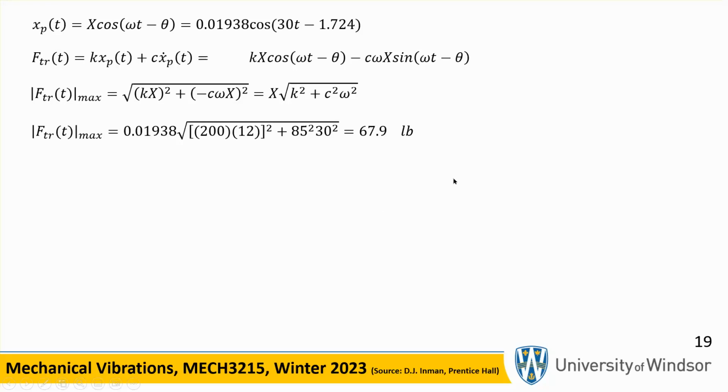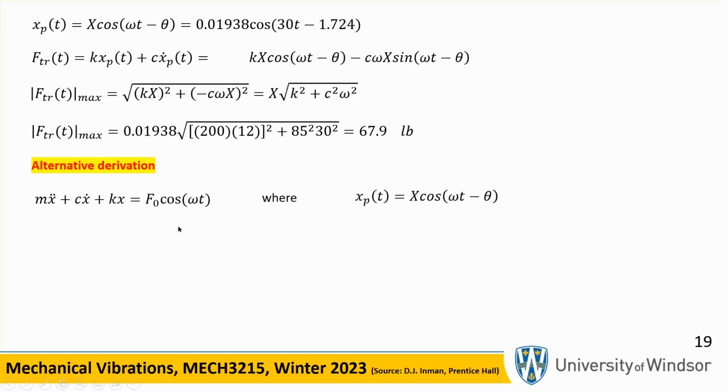Now, let me show you a different way of doing this thing. Just be patient. This is all done, but I want to show you a different way of doing it. This is the mother of all equations for the system that we have. We just said that it is this. Last hour or so, we have been haggling with each other on that issue. Now, this thing is the transmitted force. It's right there. See that? Transmitted force is c x dot plus k x.